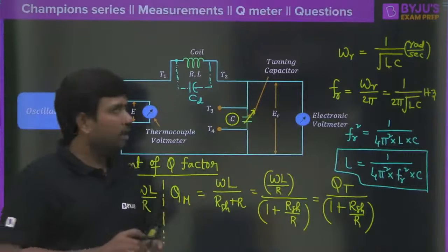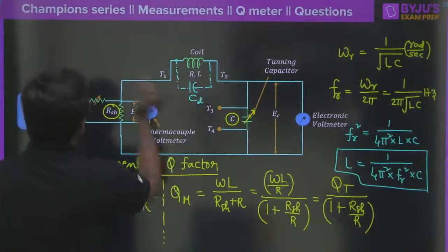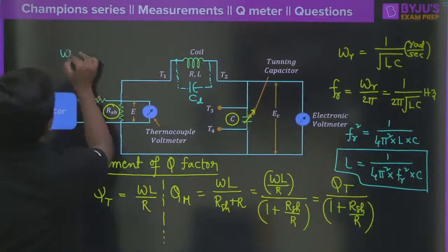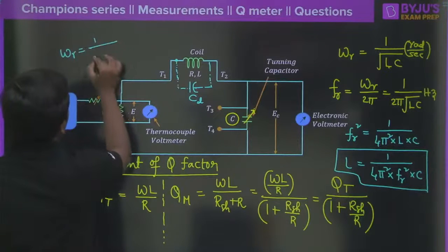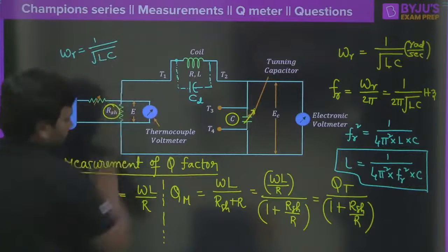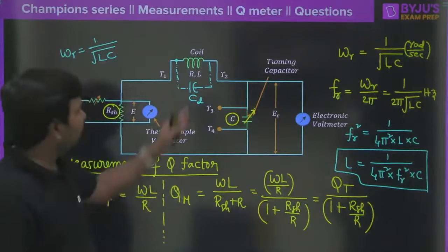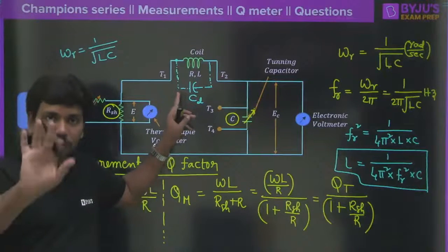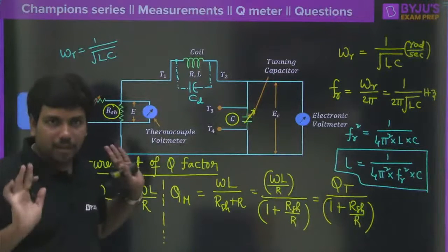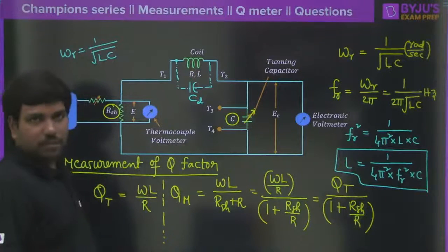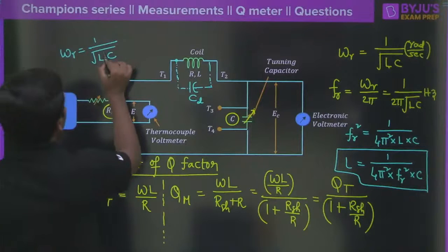the resonance. Earlier, when we don't write CD, we have simply taken that resonant frequency is equal to 1 divided by under root of L into C. Correct? This is what we have taken when there is no distributed capacitance in the calculation. But if the distributed capacitance is there, how the overall equivalent capacitance will come?